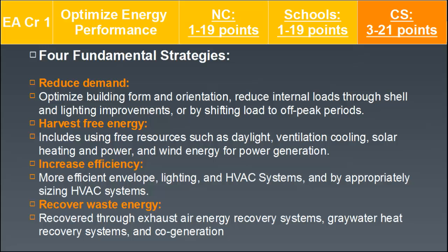You also want to consider recovering waste energy through exhaust air energy recovering systems, gray water heat recovery systems, or cogeneration. This can be important to consider when you're looking at indoor air quality and increasing your ventilation. You want to make sure to use some sort of heat recovery system for the exhaust air.